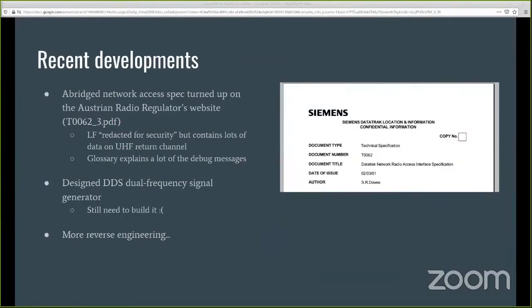So that's what I've figured out so far. I got in touch with a PhD student a while ago who did a thesis on this system and very kindly provided some details on how he'd done that, which explained a lot about what I've just explained about the nav signal format. I built a signal generator using one of the little Analog Devices DDS chips, and started feeding the clock and timing signals that his PhD explained into the receiver, and watched how the debug messages changed. Eventually, in conjunction with the reverse engineered stuff, I could generate a 64 cycle signal, which it would lock to and then complain that the clock data wasn't valid. So it had a valid trigger, but no valid clock.